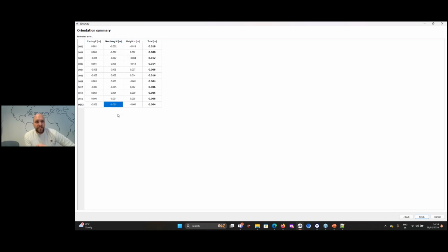But from practice, from practical experience, I can tell you that what we usually do, we just usually look at the highest ground control point error, and then we say the final accuracy of results is probably as much as the highest error here. So in that case, this is now about 2 centimeters.